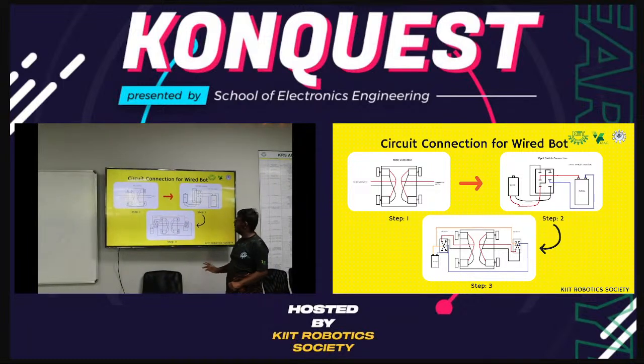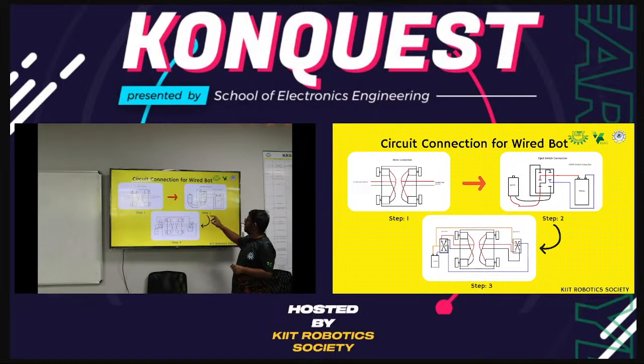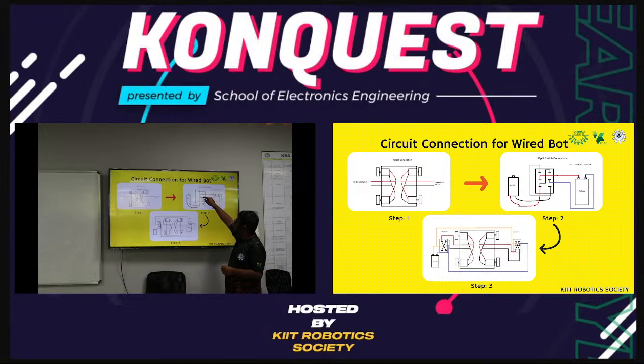The motor is connected to the lower points. When you push the forward button, the circuit will connect from the left side lower point to the middle to the right side upper point.